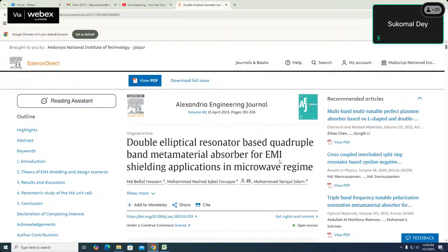How will you see the temperature distribution? Because FSS is continuously getting the signal, and you will find it in one of our journal papers. FSS is continuously absorbing the electromagnetic wave. Now, how is it dissipating the signal? Basically through ohmic heat dissipation, correct? So you illuminate the surface with the same source, and you can use an IR camera to see the temperature distribution. That would give you the actual story about your design.